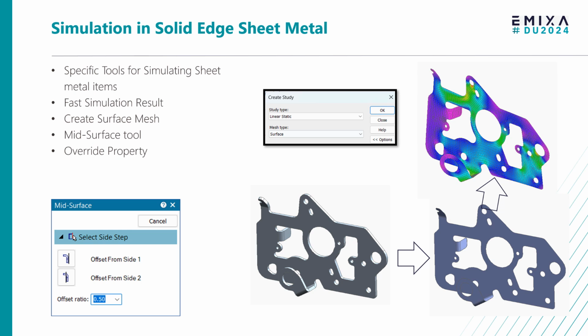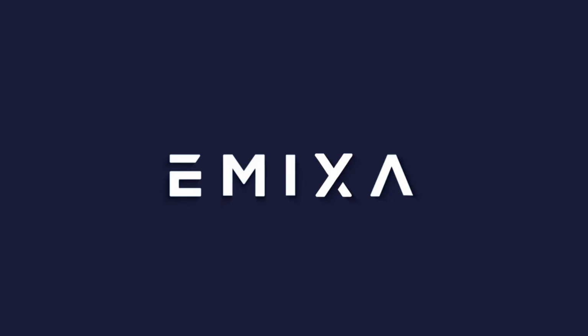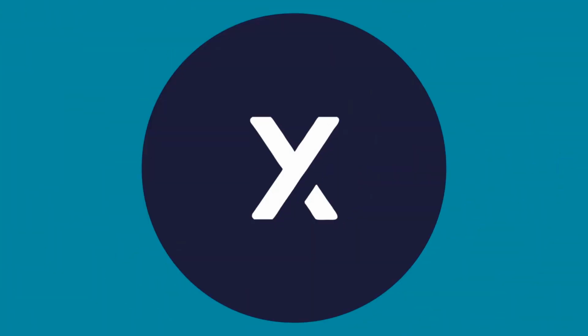So what we do, we create our surface mesh, we use what we call the mid-surface tool, and we can also use a command called override property that allows us to go, well, there's a part on here that's not as strong as it should be. What happens if we thicken this up? So it allows us to, in a couple of seconds, go and change the thickness of a part and resimulate that part. Let's have a look at that.